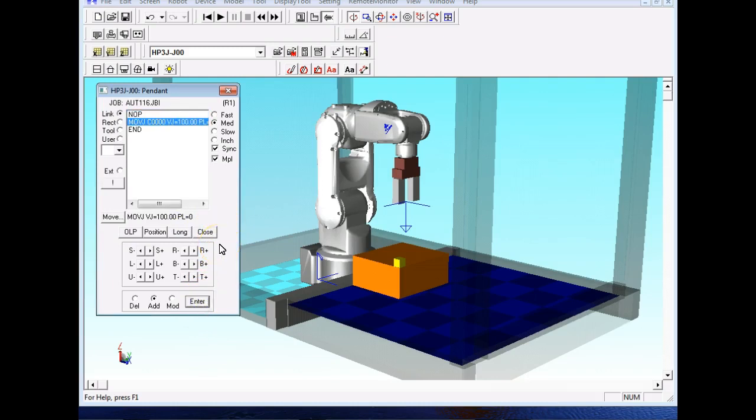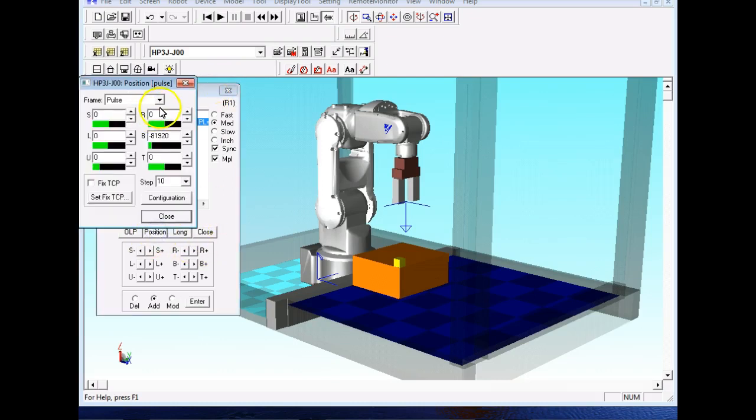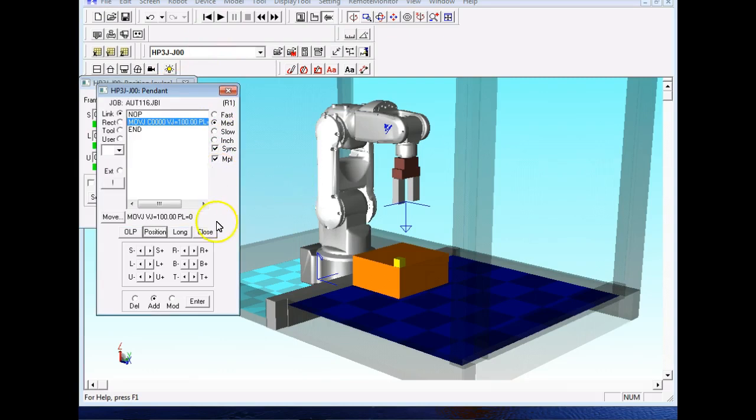into the program. So all the information that's relative to that point is stored in the program. Now we don't see that information, but this is the type of information that's actually stored. So I think this robot actually stores the encoder. So it saves this, and it tells the program where the location of all these different axes. And then what I can do is I can jog the robot. So here, and what we'll do is we'll jog it in what we call world mode. And this is XYZ.